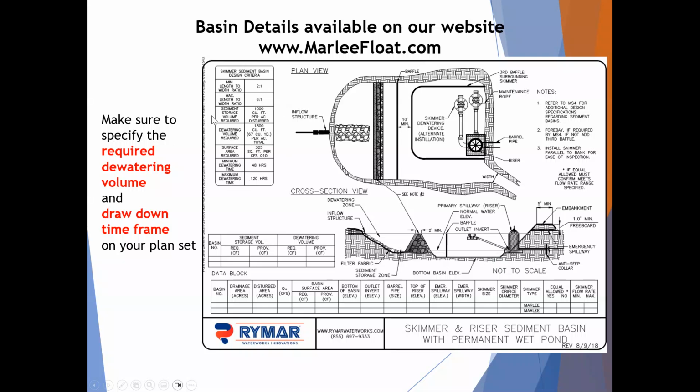All of the details have a basin design criteria that you can adjust to your specific locations, which will include sediment storage volume if required. That would be more of a permanent pool situation. Dewatering volume, that's going to be for pretty much every location is going to have a dewatering volume required. Surface area required. And here's where you set your time frame for your dewatering, so that when it gets reviewed, you're reviewing a range of time frame, not a set time frame.